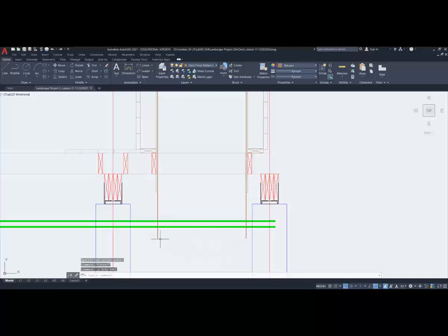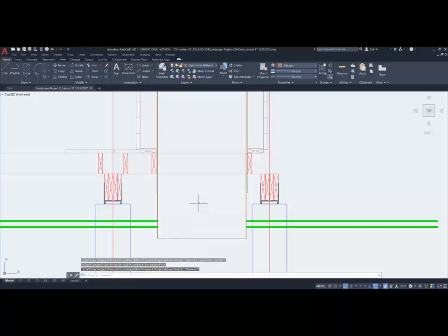So what we're going to do instead of extending that line is draw a line here. I'm going to change its properties so that it appears as a hidden line. I'm going to take these two lines, which are basically the grade, and change how they look inside of this. Let's first of all stretch. So let me get into the stretch command here. This grade line, both of them, just so you can see it going further beyond that edge. We don't see grade back here. I will trim to that and that. And that should indicate to the builder that something's going on in here. This is now hidden. Grade actually comes up into this area.